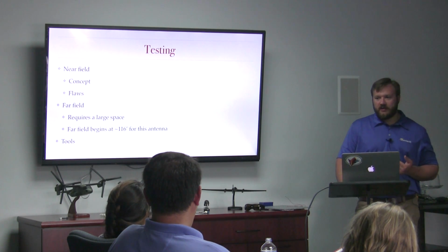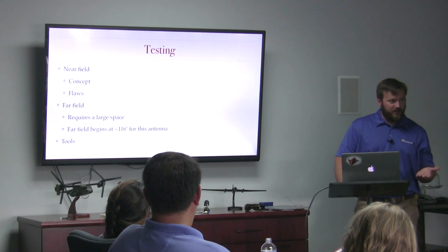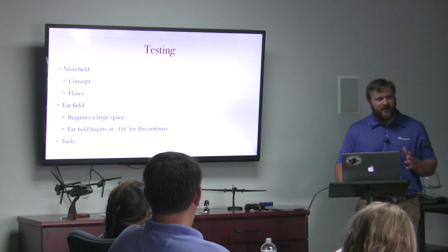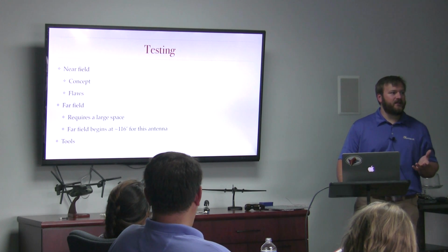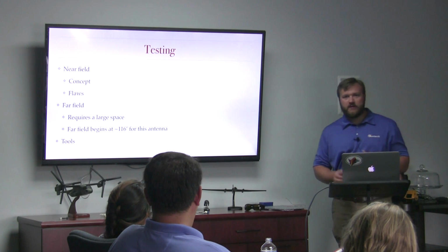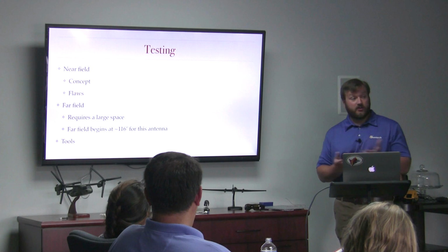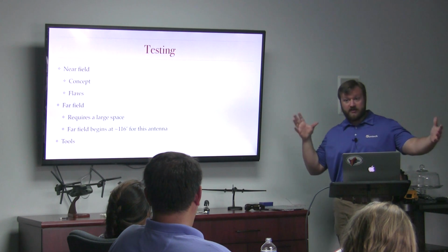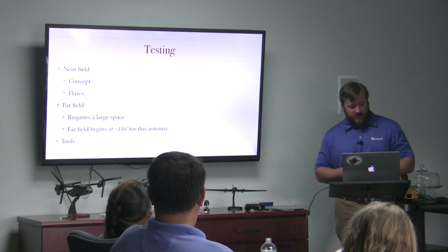need to be phase coherent, your transmit and your receive, and there's some mathematics behind the reconstruction of it. There's some labs we work with that do that. It's really not the easiest way for us to deal with it, for the folks that are already set up for it. So we do have a far field range that's about 500 meters long, and where we're going to mount things will be about 400 meters of separation, which will get us well into the far field for this project.